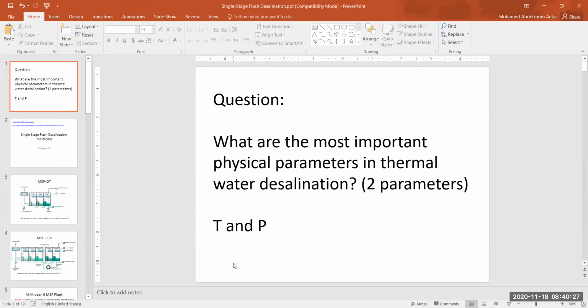What is the reason? Because we are spraying seawater outside the surface of the tubes, and we are concerned about the formation of scale. So to avoid scale, you need to keep the temperature as low as you can, and the lowest possible there is about 65 degrees centigrade to get a decent production.